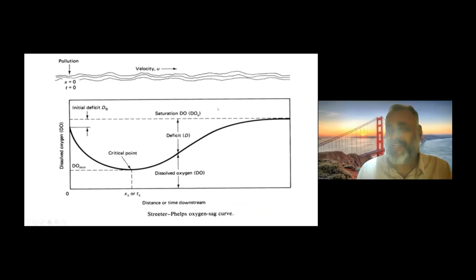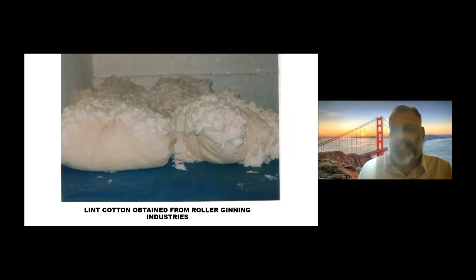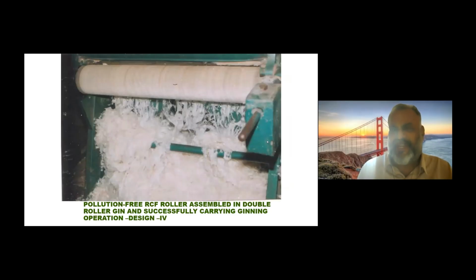Presently, what is being used in our country is chrome composite leather, which is a foreign matter. Any material which is not relevant to seed cotton, foreign matter, is a serious problem. So, for example, the seed cotton is ginned in this machine, and this roller, which is an important element of the cotton ginning process, and these washers are made up of chrome composite in our country.